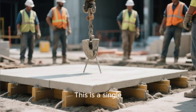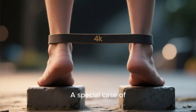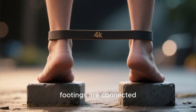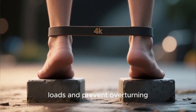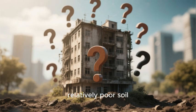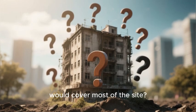This is a single, large concrete pad that supports two or more columns. A special case of this is the strap footing, where two isolated column footings are connected by a concrete beam or strap to help balance uneven loads and prevent overturning. But what if the entire site has relatively poor soil, or the building is so heavy that individual footings would cover most of the site?